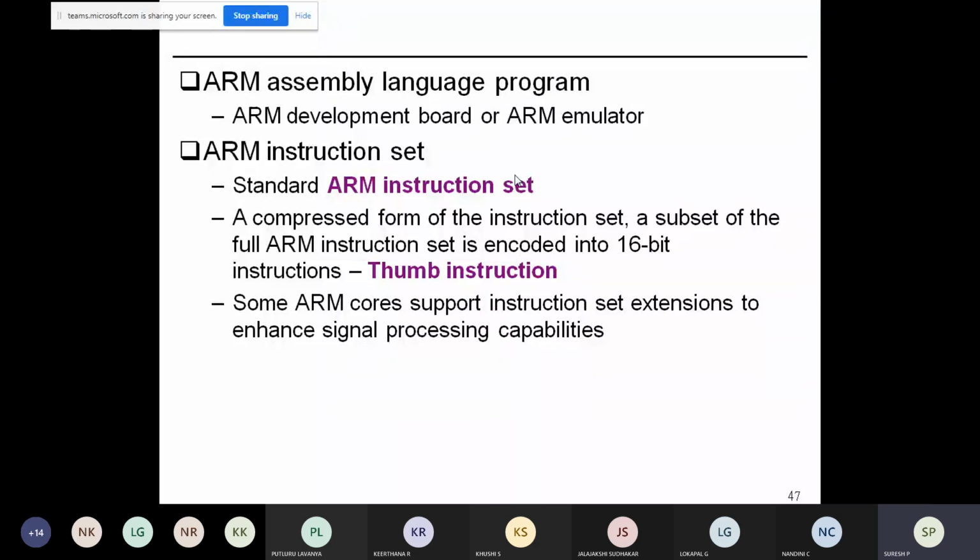First, the request has to be placed on the bus. The bus has to request the memory location. From the memory location, that instruction's binary value is fetched from memory to the processor. So it has to access 4 times for a single instruction in ARM instruction mode, when your ARM processor is working in ARM instruction mode.